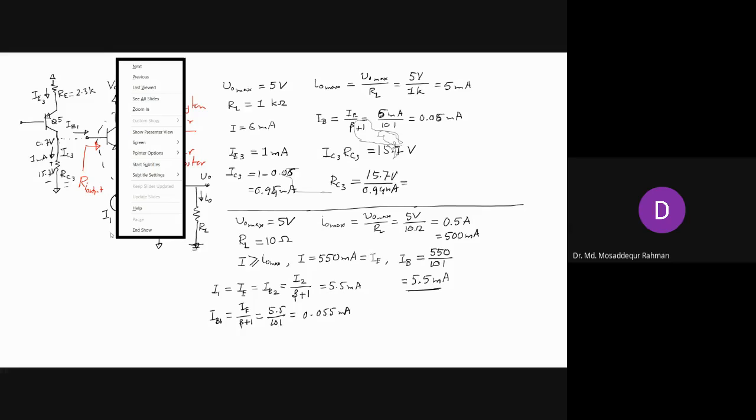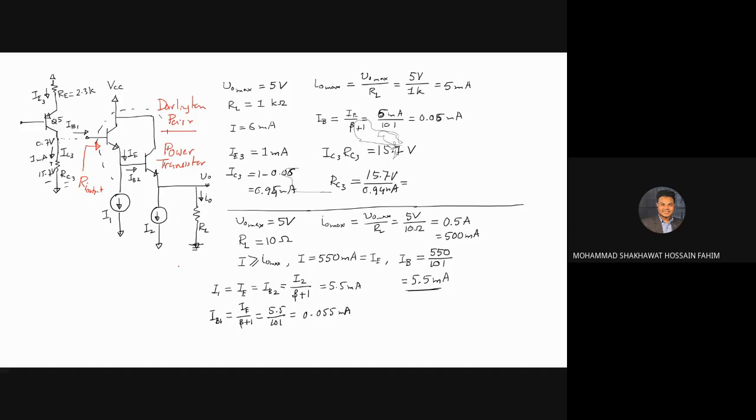But these have metal casing and are big in size, like the voltage regulators. Not all voltage regulators have metal casing. It depends on the size and the requirement of current and voltage. If they have to deal with high current, high voltage, then they come with metal casing. Otherwise, for low current, milliampere range, they come with plastic casing. Yes, sir.